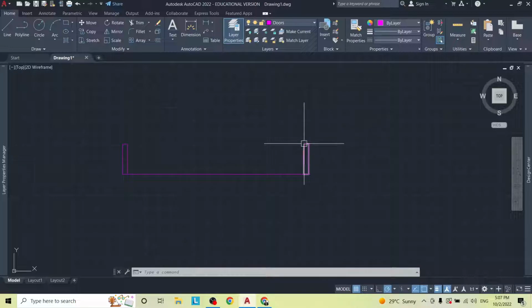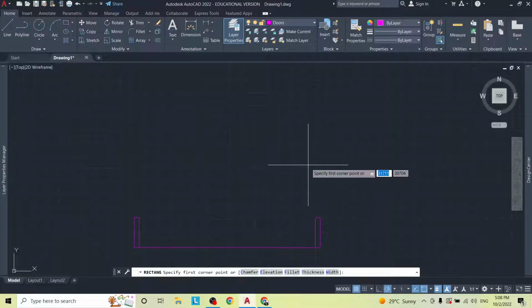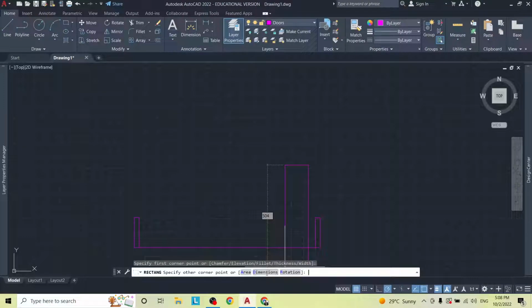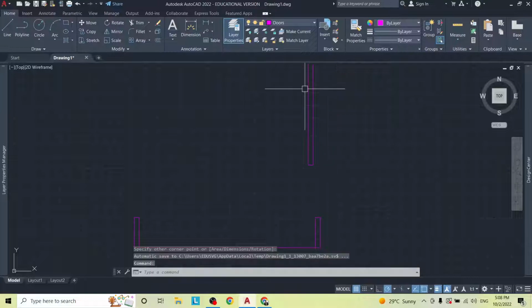So now on the inside of it, we actually want to show the door. So the door is basically going to be shown as a rectangle, an inch thick by the same 900 millimeters, because this has to close up this whole space. Alright, so we're going to draw the door in an open position using the rectangle tool again. We're going to click once, and then we're going to go down to dimensions, and we're going to put 25 millimeters, enter, and then 900 millimeters. So now when we click, if I go upwards, we click.